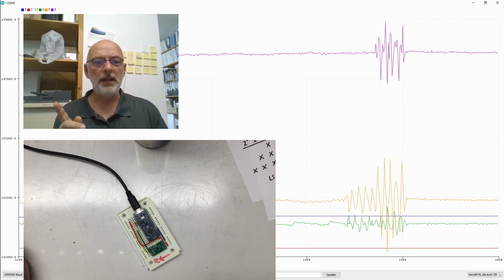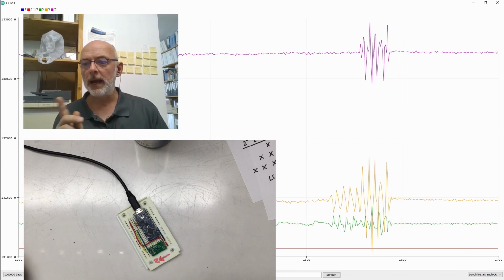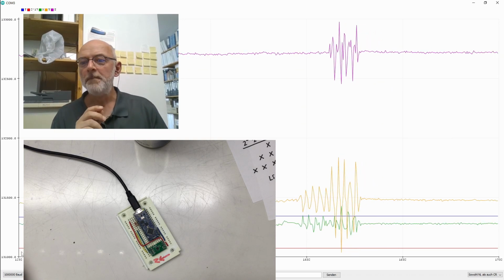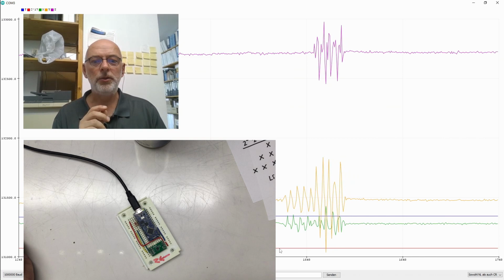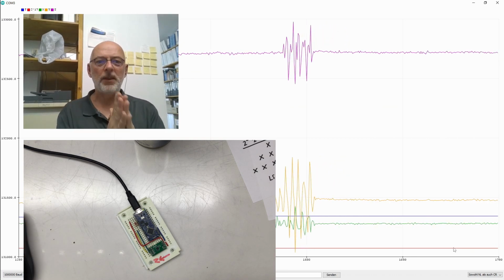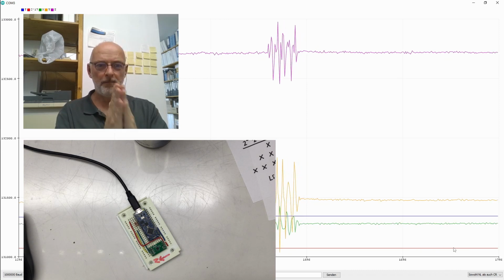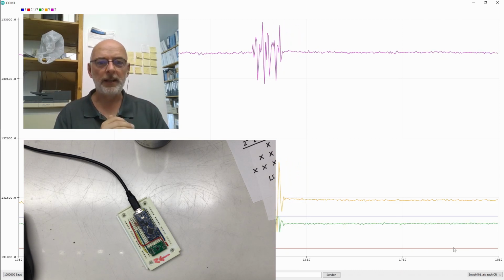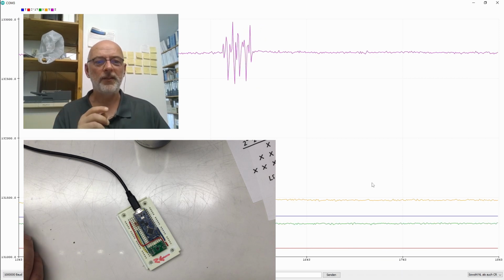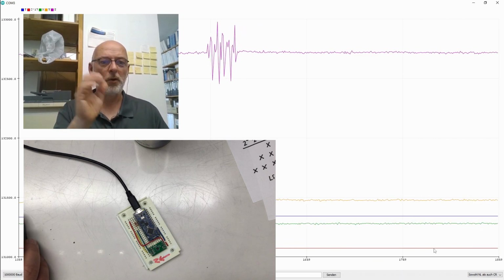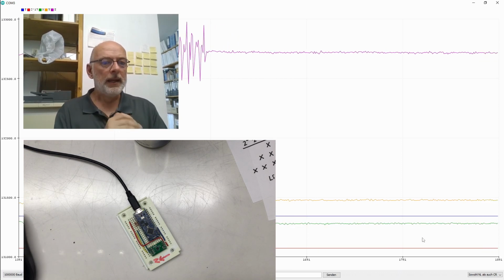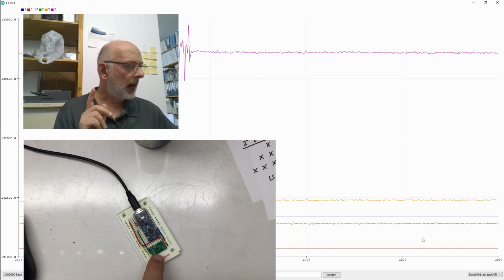Then we have here the temperature curve in blue and a little bit scaled. That's not really degrees Celsius. And here we have our 2 to the power of 17 curve, which would be the mathematical middle of our 18-bit value. So you can already see our Z sensor is far off with this 0 point from the ideal. Anyway, if I heat things up now,